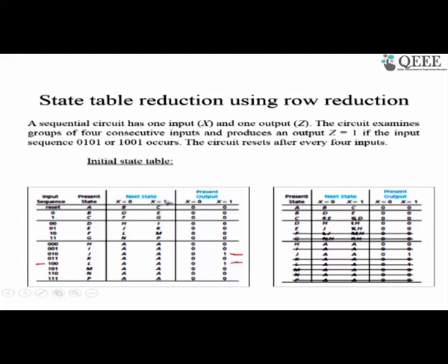It has a large number of states, which is not an optimal one. Now we will reduce it. How do we reduce it? We will look for what are called equivalent states. 2 states are said to be equivalent if on getting the same input they go to the identical state by producing identical output, which means that their behavior is the same, so they are equivalent. You don't need 2 separate representations for it.